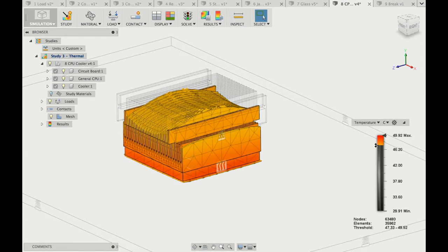is kind of rounded. So it probably would make sense to not make the cooler a cube type of cooler, but make it more rounded, because it will be much more aligned with the way the heat is transferred. And now it's the designer's decision. Would I make a cooler that would be more expensive to produce, because producing this one is really cheap?